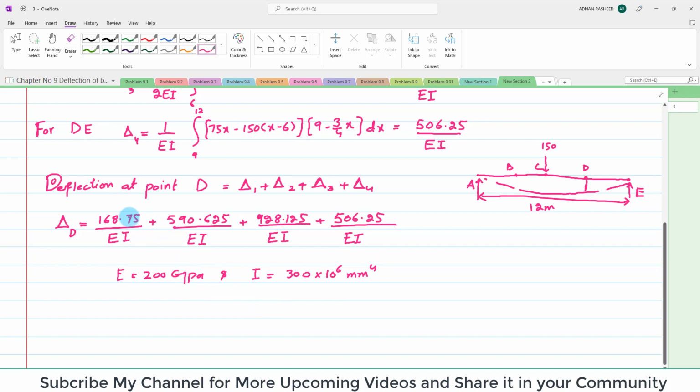So you can put the value in this equation. When you sum all this, it will give you 2193.25 over EI. So this is the deflection at point D. So deflection at point D is equal to 2193.25 divided by 200 into 10 to the power 3, which is in megapascal, clear?